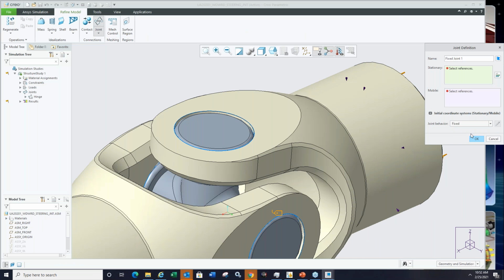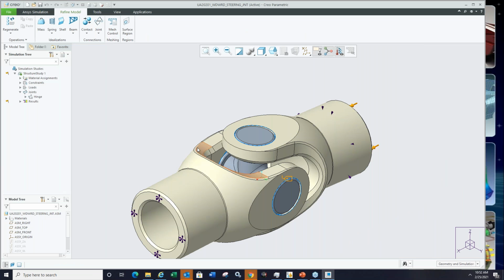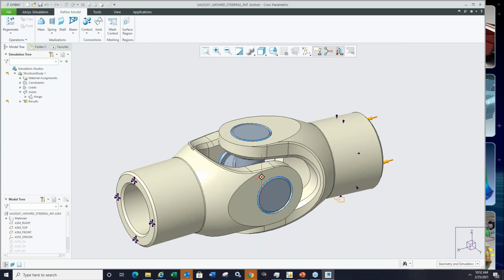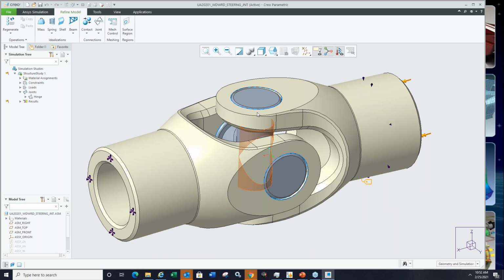So these are some of the advanced options that you could potentially use. And I remember in Creo Simulate and some of the tools that I've used, I had to do that with a little bit of additional work like rigid link or weighted link, or sometimes I had to create multiple spring elements. There's a little bit of additional work that I got to do, and it's nice that that behavior can be captured really quickly there.